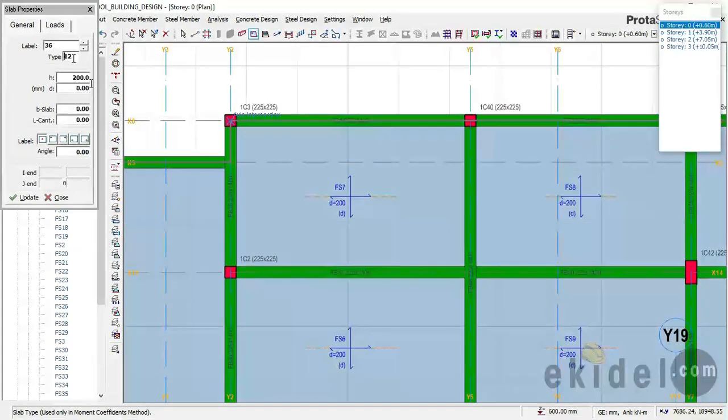So once you pick 2F right now, on this place called length of cantilever, which is L cant, you have to put a toe slab. The length of toe for a retaining wall starts from 500, so 0.5 to 1 meter. To avoid coming back to repeat what I've just done, I would advise you just use 1 meter, which is the maximum, or you can stick to 850 or 750. But in this case, I'll use 1 meter as my length of cantilever.